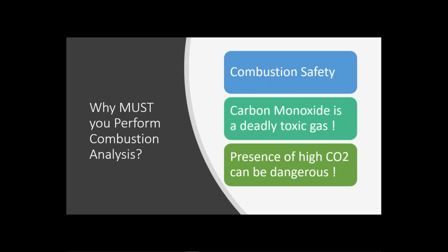So let's talk about the importance of why you must perform a combustion analysis. Number one, combustion safety, absolutely. Carbon monoxide is a deadly gas, and carbon monoxide is a byproduct of anything combustible. And presence of high carbon dioxide can be dangerous as well. Carbon dioxide is the output of combustion. Remember what we do. We breathe in oxygen as humans. We exhaust carbon dioxide as humans. Plants, house plants, take in carbon dioxide and give out oxygen. That's the natural procession of things.